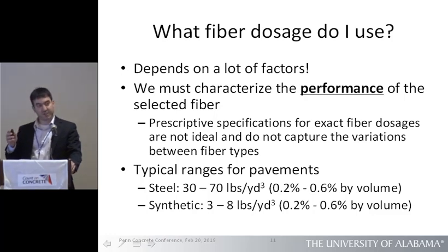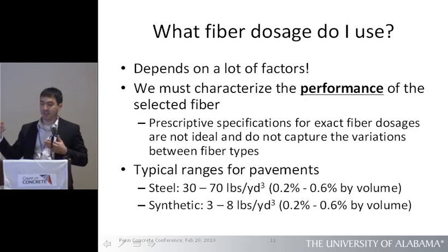A lot of times these fibers are added either at the batch plant or into the truck. Sometimes they're held together with dissolvable bands or in dissolvable bags. The state of Oregon actually does not allow you to toss the whole bag into the truck. You have to open the bag and dump it, or not use a bag at all. A few other states have requirements on how to actually add the fibers into the mix. But regardless, these are the typical ranges of fibers we add for concrete pavements.